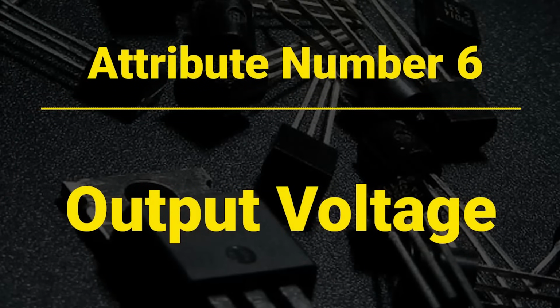Now, we are going to shift our focus to the next attribute. Attribute number 6, output voltage. The output voltage of a regulator can be fixed or adjustable. For example, the L78XX series are fixed output regulators, meaning that the IC is designed to create a fixed voltage at the output, say 5 volts or 9 volts.